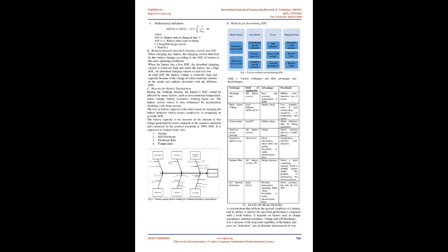2. Battery terms. A. Continuous discharging. The battery continuously delivers energy to the load, which leads to a continuous drop in the battery capacity. B. Intermittent discharging. The battery delivers energy at regular or irregular intervals of time. The energy is drawn by the motor for some period followed by the voltage recovery period. C. Rate of charge and discharge. To extend the service life of the battery, the rate of charge or discharge should not be too high. The frequency of charging and discharging cycles also affects the battery life significantly.